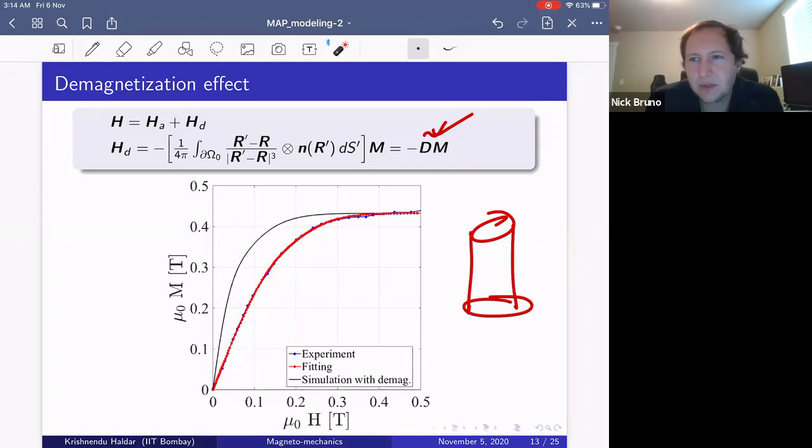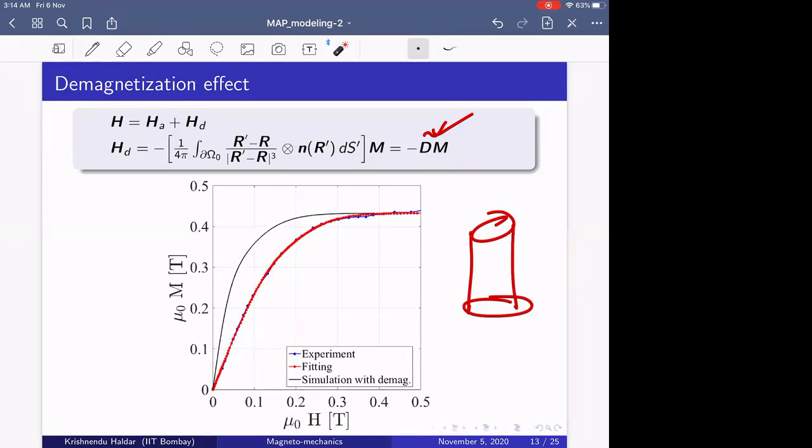I see. So it'd be kind of like iterative. Yes, because sometimes 3D is easier. When you want to reduce everything to 1D, some inconsistent effects pop up immediately. So that's really annoying. In 1D, in principle, there is no demag effect, but here you just consider this a cylinder and take the dimension, and you get the demagnetization effect for a cylindrical body, and you just apply the rest of the 1D conditions.